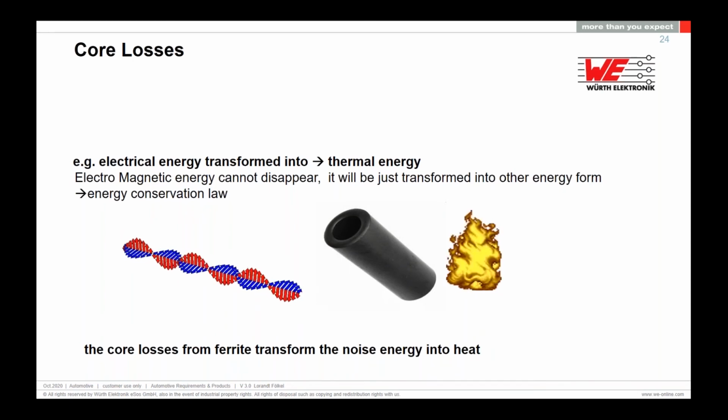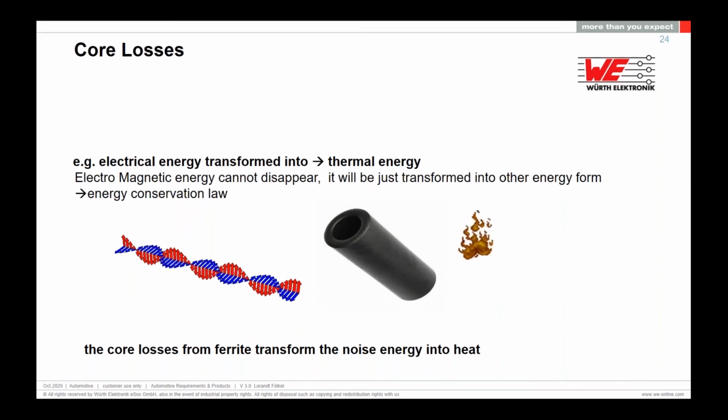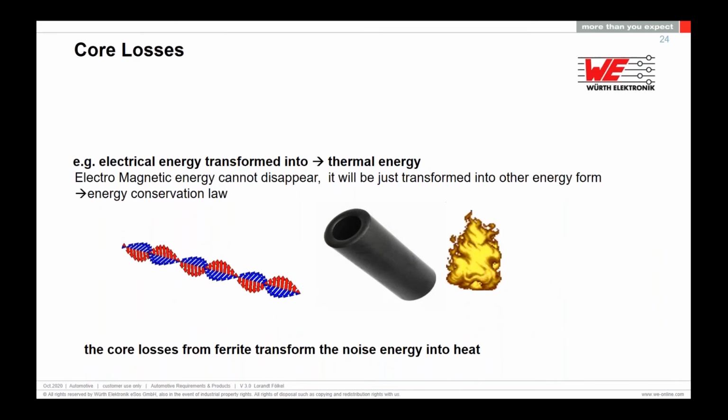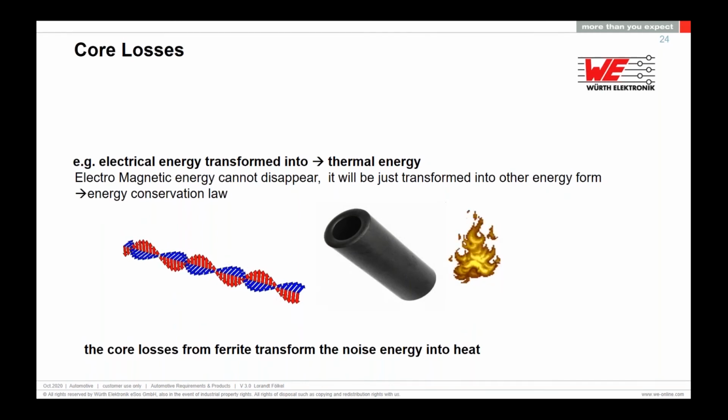By radiation it should stay cold. Please don't produce devices which make the ferrite run hot. This is not an EMI problem, this is also a safety problem.